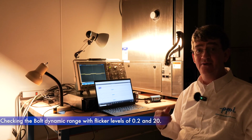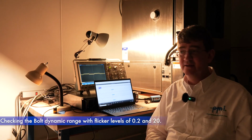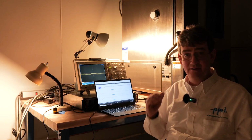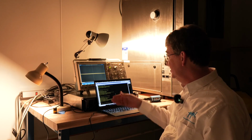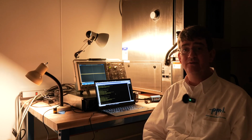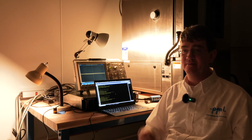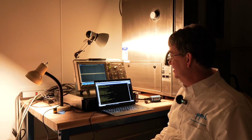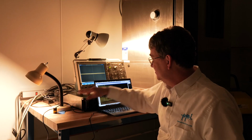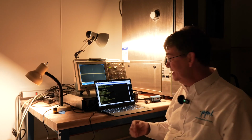We're going to check the dynamic range of the Bolt flicker measurement and also check its linearity to make sure that it is valid not just at PST of 1, but also at very low flicker levels and very high flicker levels. So we're going to set the power source to a very small change. This should be a PST of 0.2, which is the lower value that a flicker meter is meant to measure. And we set this, you can see the flicker is almost invisible. Even on the optical sensor, it's difficult to see because this is a very small amount of flicker, the smallest that's measurable for the standard.